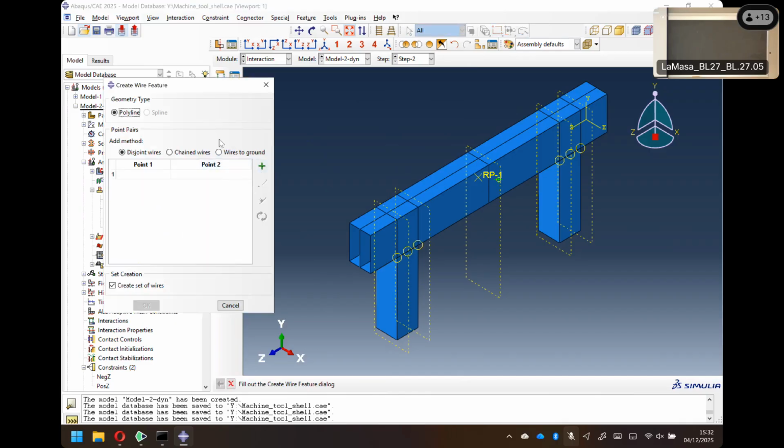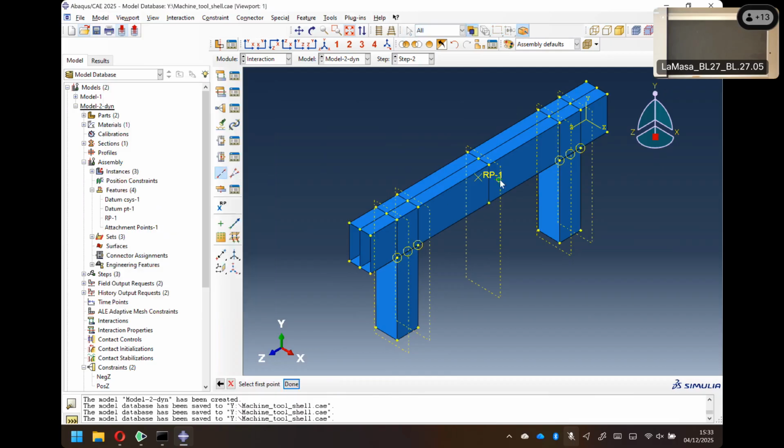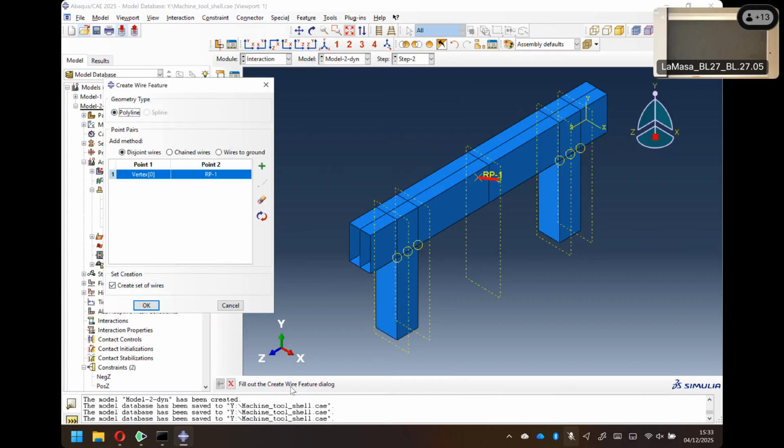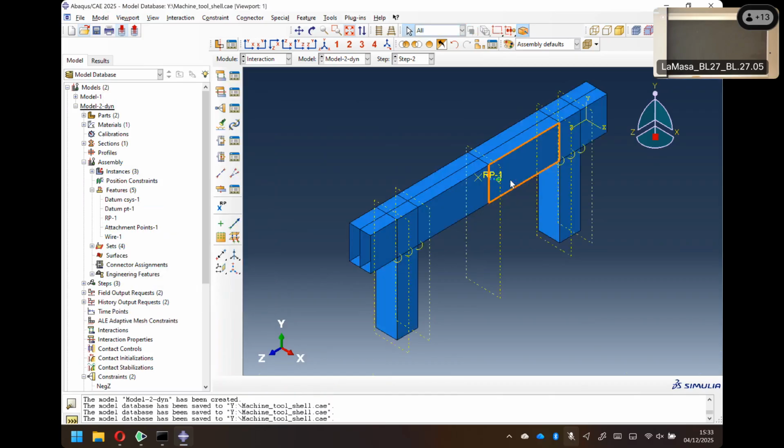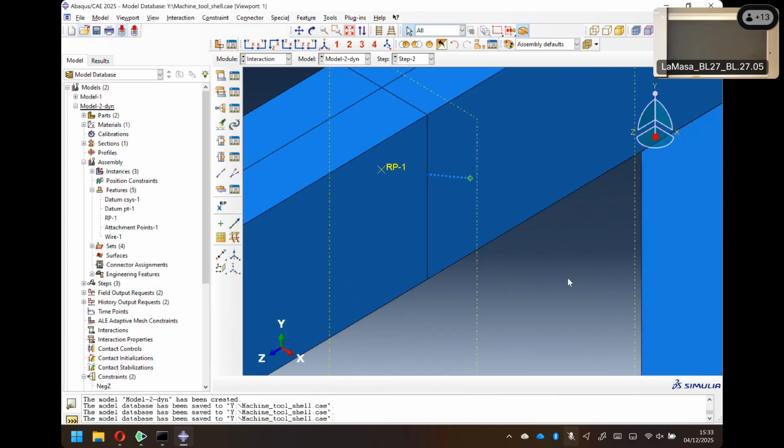this, do you want me to repeat some stuff? This opens up, add, from the green X to the reference point 1. Done. Okay, and now if I zoom in, I have this blue dashed line that goes inside the crosshead because it's connecting the 2 points. This is a line, this is now a wire, purely geometrical, it's still nothing mechanical.